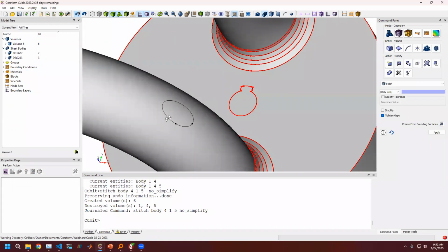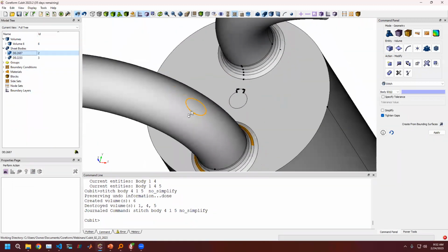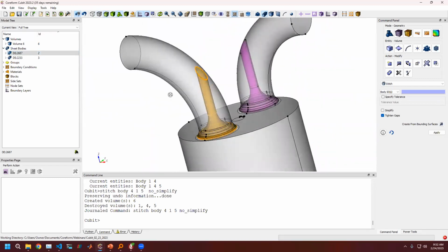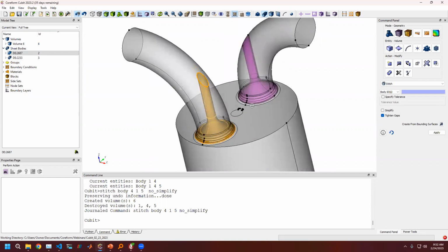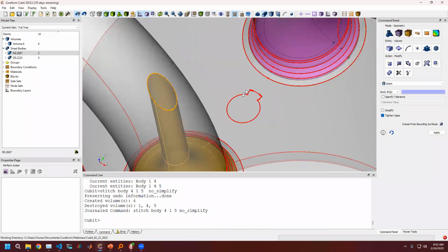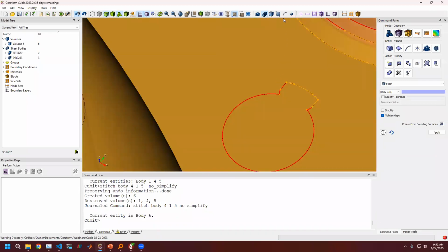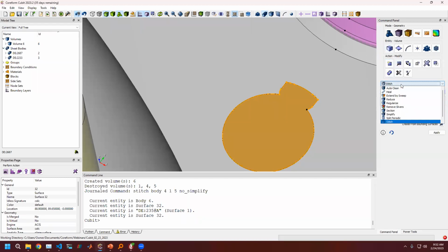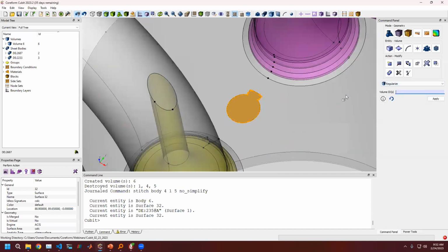What you're seeing here is these valves on the inside that are bringing their surfaces up. Now I want to get rid of this, right? I've got a plane surface on a plane surface. I don't need that anymore. There's also a tool that's really helpful under volume. It's also under surfaces, but volume modify, regularize.